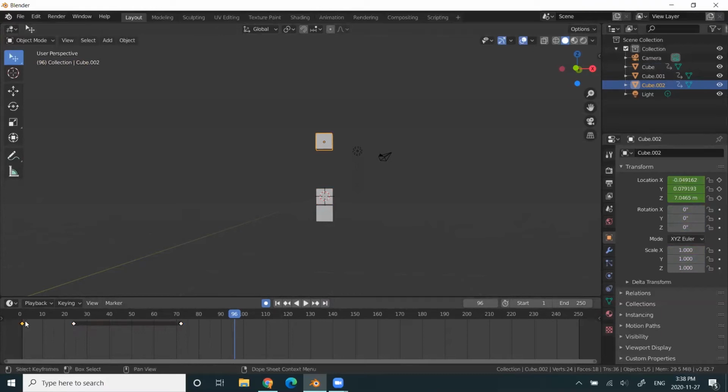Okay, I'm going to do the same thing to this object. So I selected the first keyframe, Control C, and then Control V. So when we play the whole sequence, and I can change this to go back here, if I play through the whole sequence, play animation, it'll come out, hold, and then come back in. And you'll notice that if we loop it, maybe there's not enough time for it to hold once it's together. So we can easily adjust that by going all the way here, maybe another 2 more seconds.